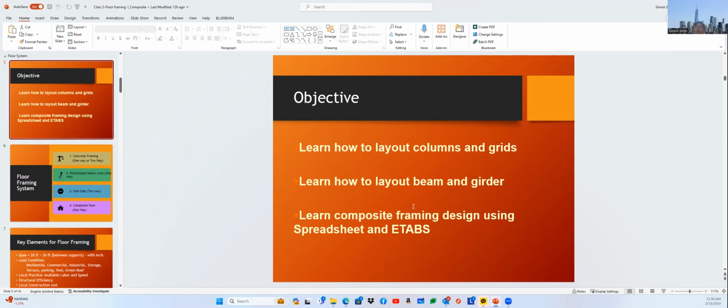I want you to remember your previous practice, the cantilever column wall. It's pretty much the same procedure. We're gonna define geometry and boundary conditions, define the load, assign the load, analyze the model, calculate the member forces, shear and bending, and check the deflection. We are following the same procedure.